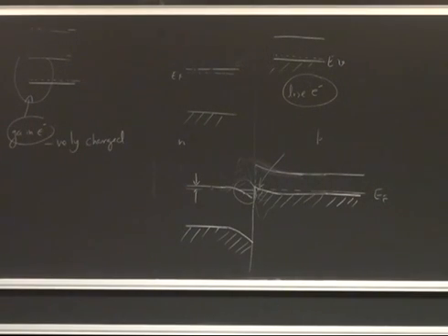Okay, so again, this structure, as we had discussed, the one thing that you can always count on is, if you have a standard depletion, then the procedure, remember, is you find the charges, and here we know that there is depletion on the n side, so that's going to give you positive charge, depletion on the p side, so that's negative charge, and they're exactly balanced.